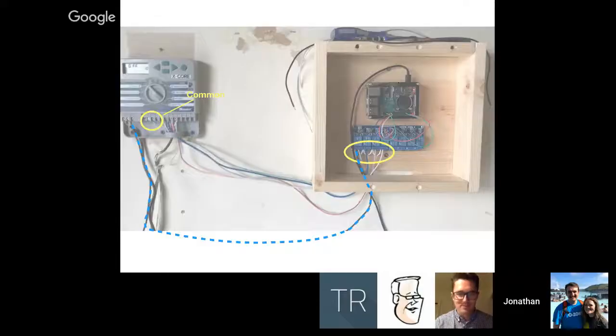Yeah. So I only have 4 zones, which means I have 4 more relays I can play with, and I actually connected 2 of my garage doors to them. Because garage doors are kind of the same thing. They're really not that smart. To open a garage door, you just have to short a line, add power to it, and take it out. And then ta-da.